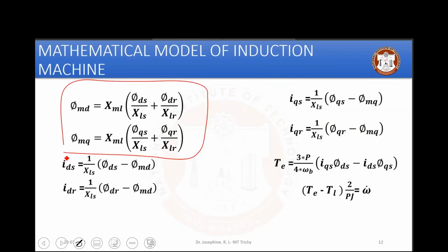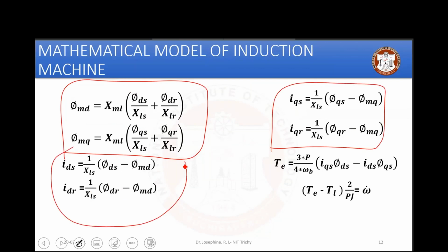And here is your flux representation, current representations of all the phases that I have just mentioned. And your torque, this is very important. This torque is actually IQS times psi DS minus psi QS times IDS. Remember, assume that this is some constant. Ignore that. This is your base speed.